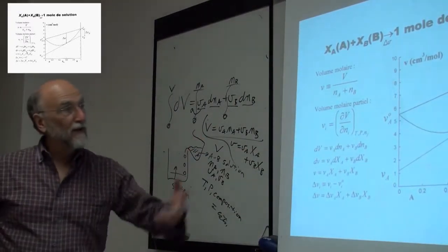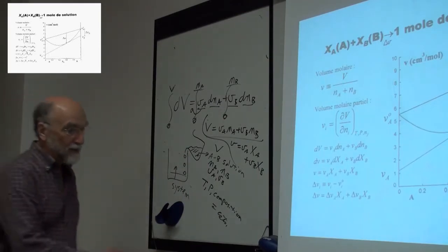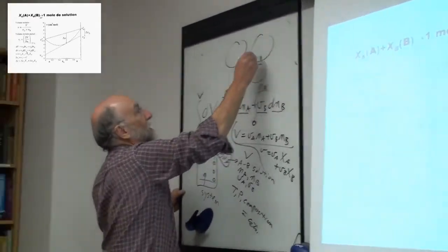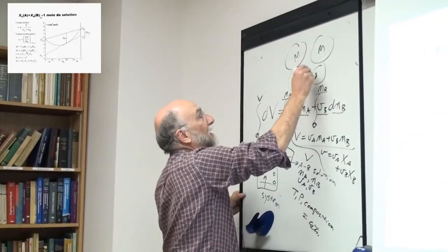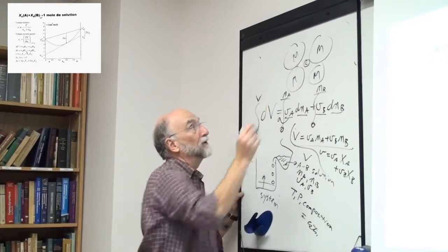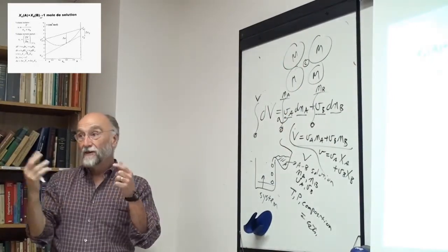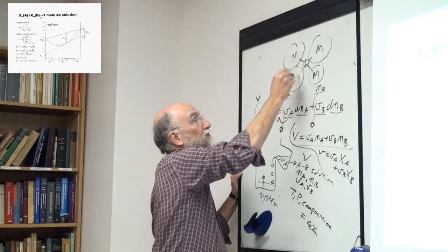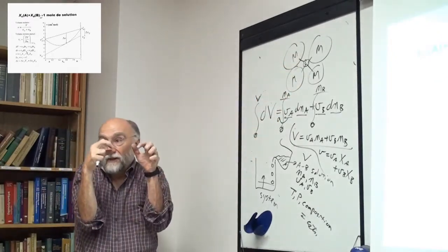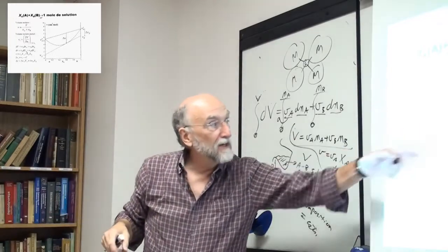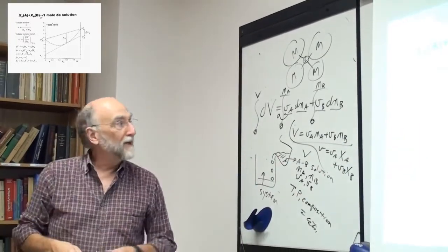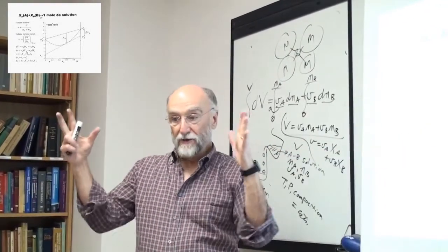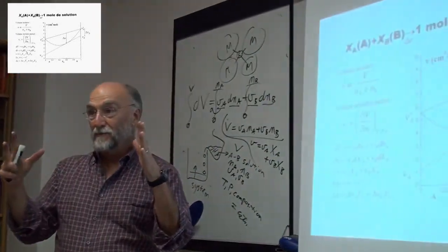Supposing that you put in something like carbon, I don't think this is quite the case, but let's suppose that you have a lattice of some metal, M, and into that lattice you put a small nonmetal like carbon. First of all it goes into the interstices, so it doesn't expand the lattice at all. And you form very strong bonds here. So what it actually does is it pulls it in a little bit. Now what happens is you're going to get a negative partial molar volume. So you're going to add this material to your metal, and you're going to find there's actually a decrease in the total volume.